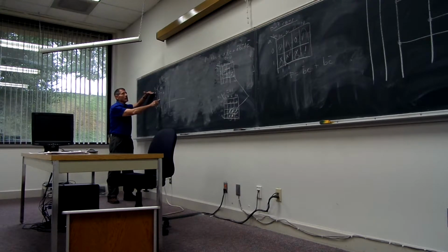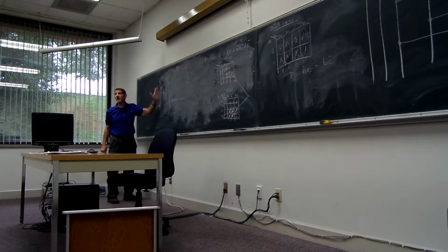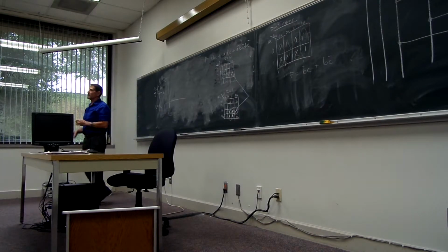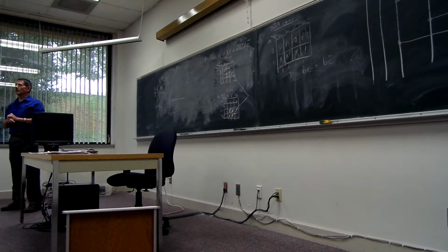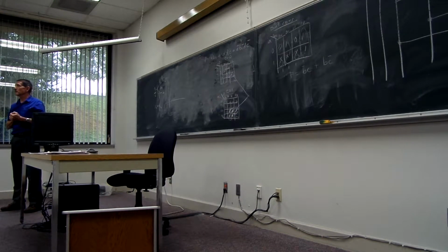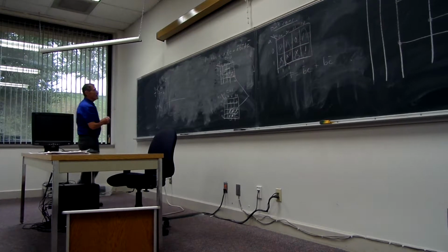If you don't put any current in, there is no current in the collector. You put a few electrons per second into the base, and it gets amplified by this beta value, or hFE as it's sometimes called, typically on the order of 100. So if you put 1 microamp into the base, you'll get 100 microamps of collector current.